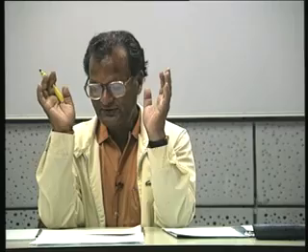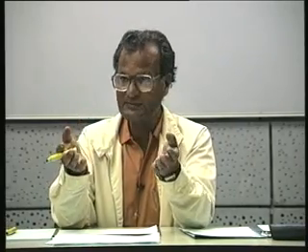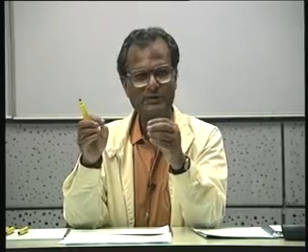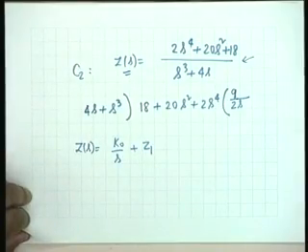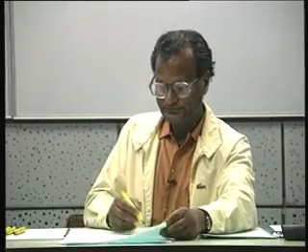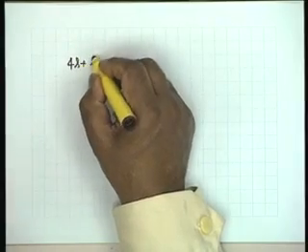But even if you do not know continued fraction, cover 1 is not very difficult, because it simply means removal of poles at the origin. If the function has a pole, remove it. If the function does not have a pole, take the reciprocal and remove it. But this is the mechanization. Okay. Let us continue this continued fraction expansion.